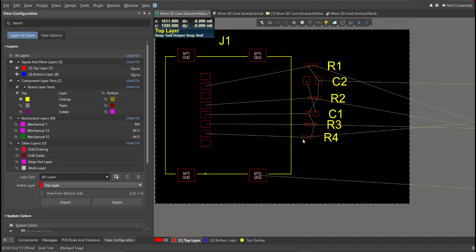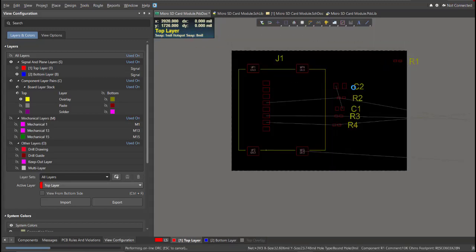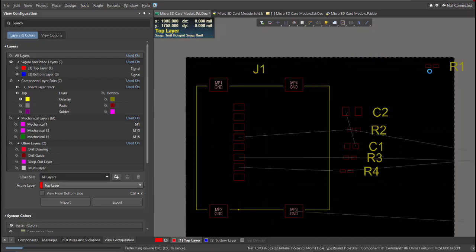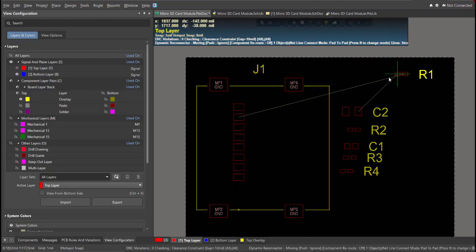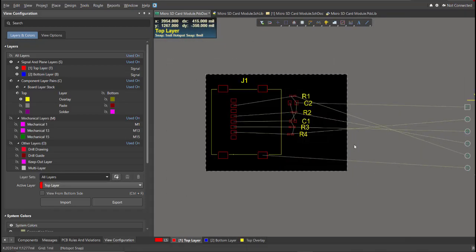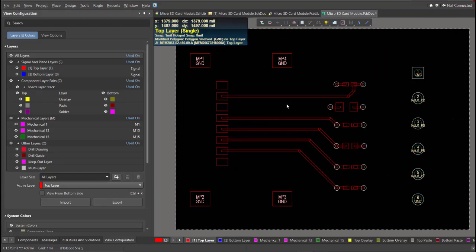In component placement, some mistakes are that the component is placed far away from its connection. When you're routing, it will be harder for you to connect the components because they are far away from each other. So make sure that you place the components near their connections. For me, a good placement can lead to better routing in the layout. Now we go with the layout.